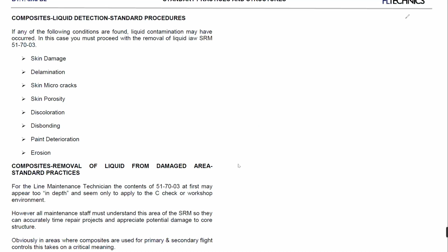Because some people are saying, oh, this is a very small dent, no need to investigate it because I know it is in the limits. Yes, you know it is in the limits, but please make it official. So the next guy will find the same damage. The first step will be, okay, there's a dent, I have to evaluate it. But before you start to evaluate, check the book. If it's already in the book, no need to waste time, correct? This is another reason why we have to mark all these dents in the book.